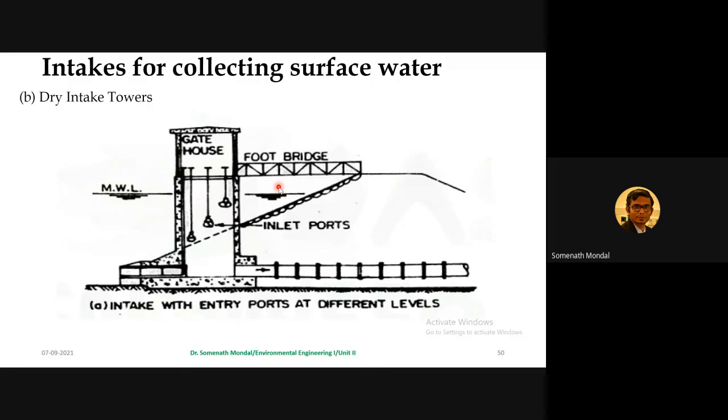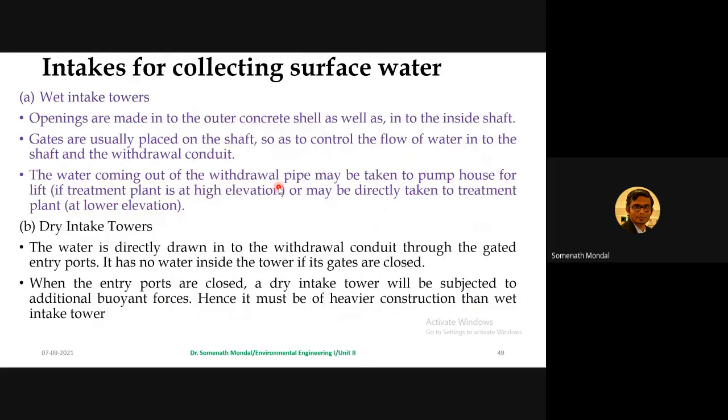It has no water inside the tower if its gates are closed. When the entry ports are closed, a dry intake tower will be subjected to additional buoyant force. Hence, it must be of heavier construction than the wet intake tower. So this is very, very important to remember. Fine.